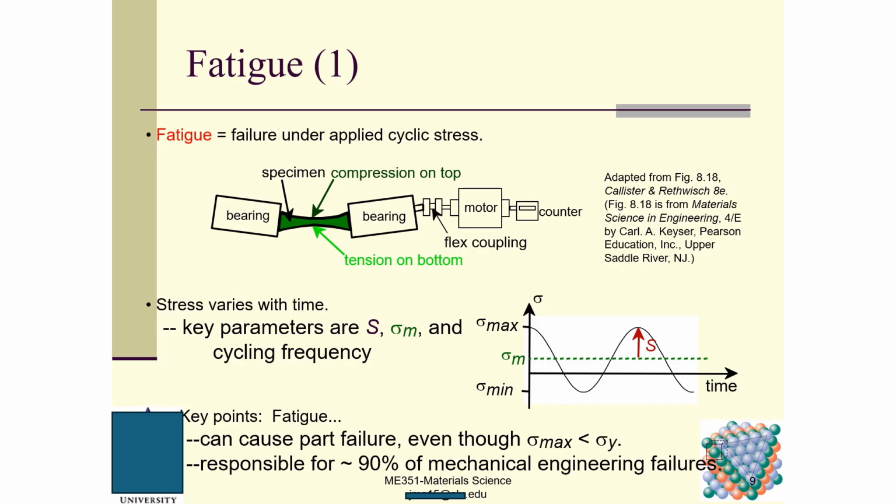than the yield strength, and it is responsible for about 90% of mechanical engineering failures. So fatigue is very, very horrible, catastrophic. It also happens without any warning, so be very, very careful.